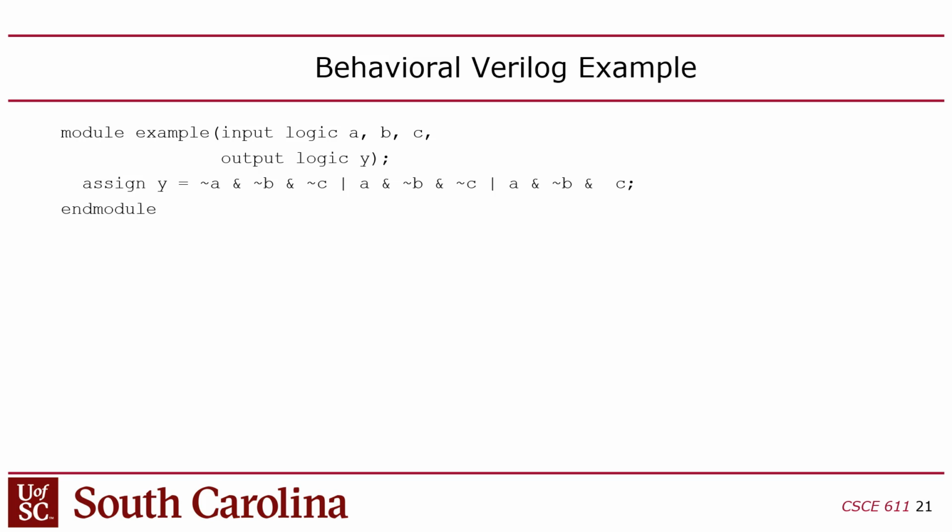The logic type allows 4 states: 0, 1, X, or Z, right? And actually there's more than that in SystemVerilog. They added different strength levels now too. You can have a strong one or a weak one, which is outside the scope of this class. There are multiple values, but it's 1 value. Yes, questions? Yeah, it's kind of a long story, but that's one of the things they fixed.